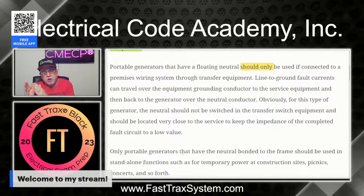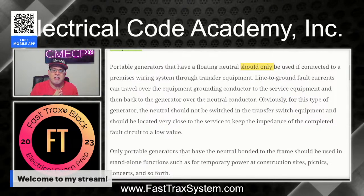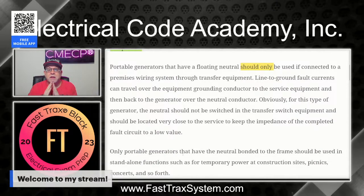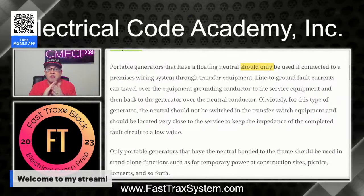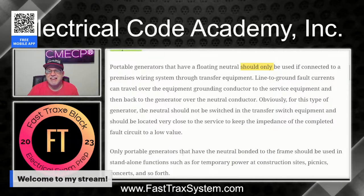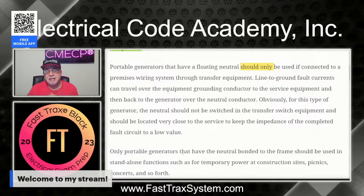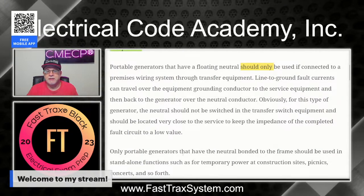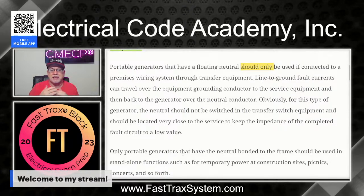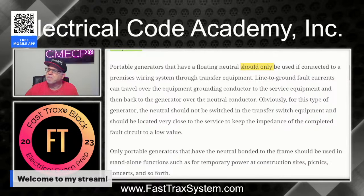And so when you have that connection and you get, let's say, a transfer switch and you don't pay attention, and you get one that doesn't switch the neutral, then you're going to get parallel paths of neutral current traveling, and that is an unsafe condition, okay? Because basically you have to understand that what you're dealing with is parallel paths of neutral current. So it can be really unsafe. But we'll look at all that in an example and kind of show you what can happen. But don't worry, we'll dig into that in a minute. All right.